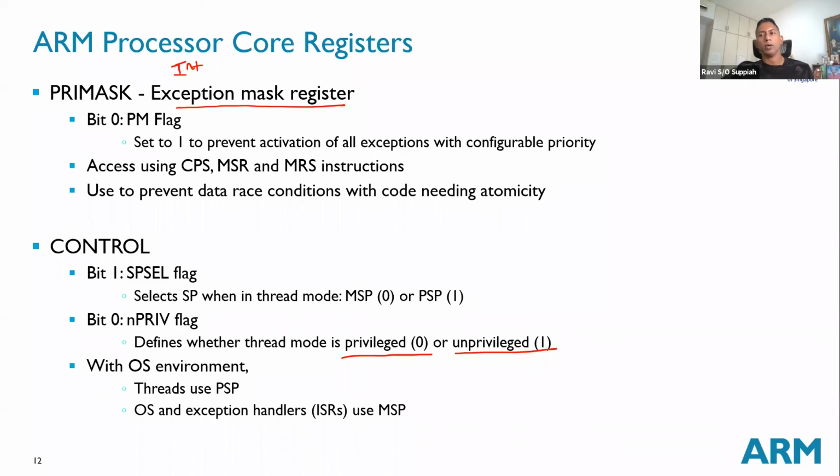The OS that runs on your phone has to have privileged access, correct? Because it must be able to do anything. But the app that runs on it, you will want to give some restrictions, correct? Or the OS itself may want to impose some restrictions so that it cannot try to mess with certain peripherals or certain memory regions, because those are reserved for the OS. So you cannot allow access to that. Your app running on your phone is generally in unprivileged mode because it cannot just try to take over your phone. Certain things are blocked. That is where the privileged, unprivileged mode comes in.